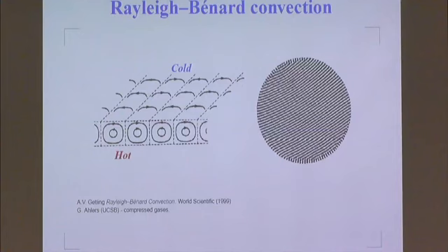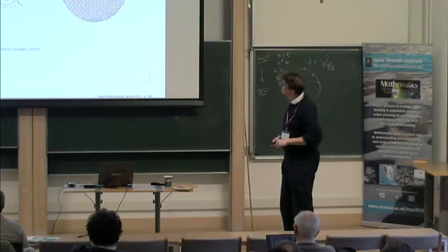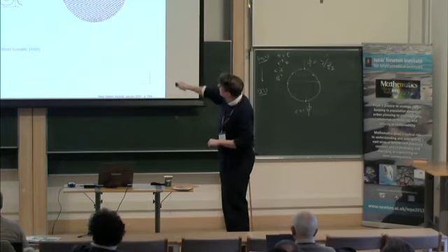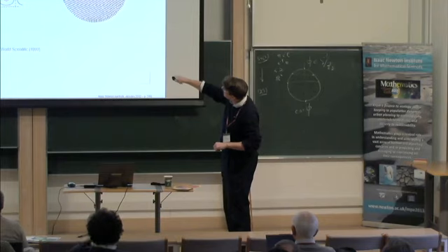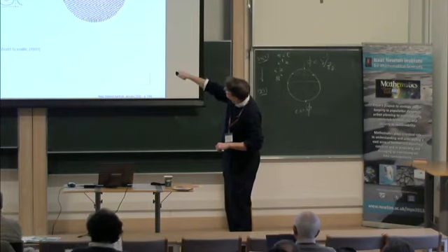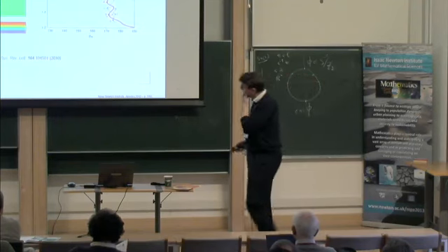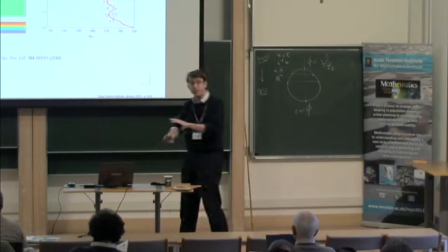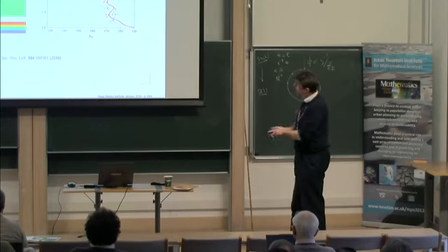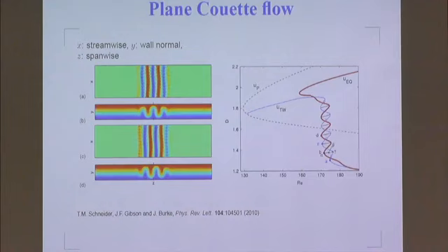It's a viscous fluid in between, and above some critical driving temperature, you generate this instability where the system is trying to equilibrate the different applied temperatures and even them out as quickly as possible, and it has to do that at a higher rate if there's a higher driving temperature difference here, and the initial conduction profile is unstable.